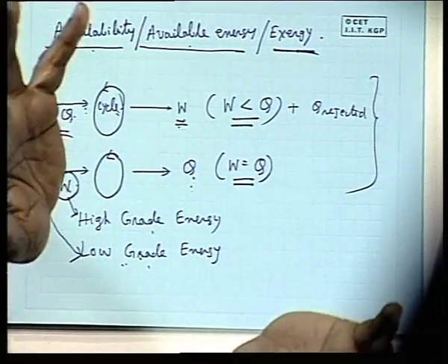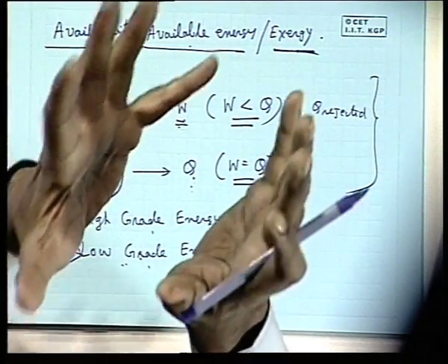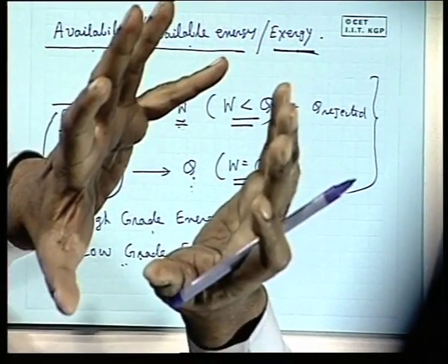But this is not always true for heat energy. There are other forms of energy, as I told, that energy stored in a system, internal energy. You know there is a point function. Now this internal energy, again we come back to the earlier discussion, has two divisions. One is the mechanical form of internal energy, that is kinetic energy, potential energy. If you leave aside that form, what is the other form of internal energy? It is intermolecular energy. That is because of the temperature of the system, because of the chemical bond energy of the system. If a fuel, you know that within a fuel there is an internal energy, which sometimes we ascribe as chemical energy. When you come to the thermodynamics of reactive systems, these things will be clear. These are all internal energy stored within the system.